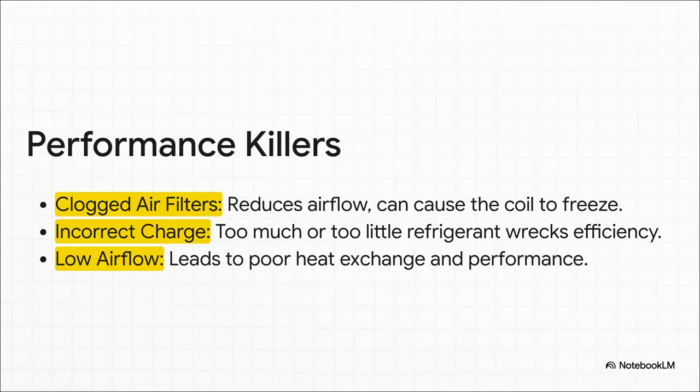So what are the common ways these things fail? For your exams, just remember these 3 killers. 1, clogged air filters. Super common. It chokes the airflow and the indoor coil can literally turn into a block of ice. 2, wrong amount of refrigerant. Too much or too little, and the whole system's performance just goes down the drain. 3, low airflow in general, maybe from a dirty fan. If you're not moving air, you're not moving heat.